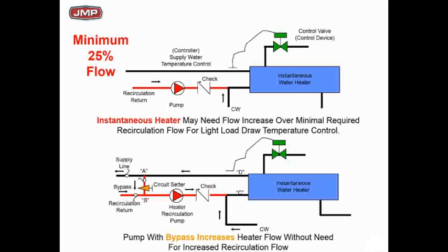So now it sees the actual temperature, and you could actually look at load a little bit better because now you've got a minimum flow rate of 25 GPM, not 1.5. And that's the whole issue. So how do you fix some of those things? Well, at the bottom, you see one idea. You're going to have a bigger recirc line for 25 GPM.